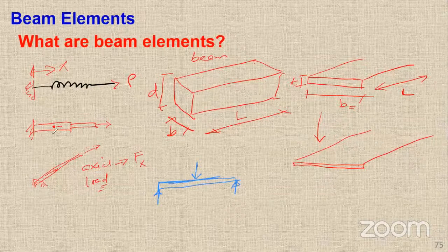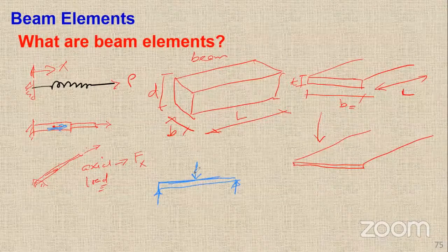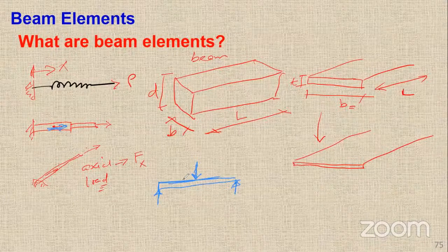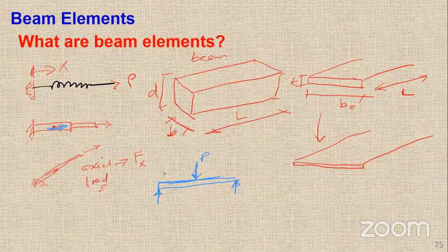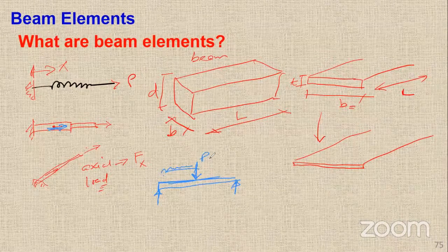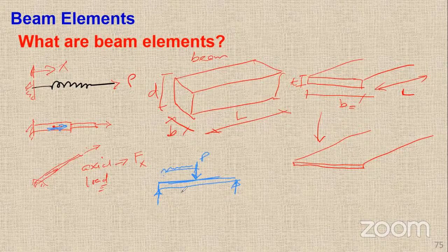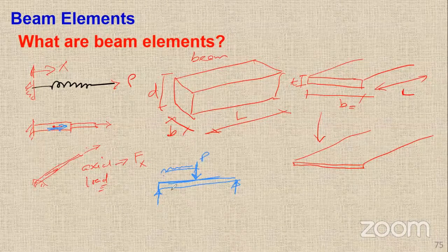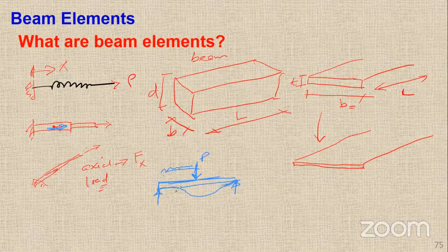Axial, of course, is along the axis of the member, while this is perpendicular. So transverse loading could be a point load or a UDL, a uniformly distributed load, whatever the case. Because of this nature of loading, there is the action, which is the load. The reaction, or the output, is that this will cause bending, based, of course, on fixity here. That's why I'm sketching like this.